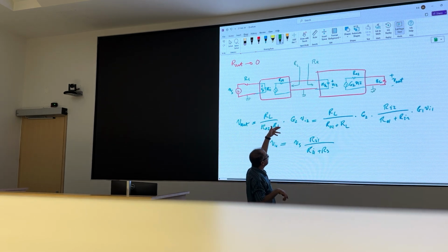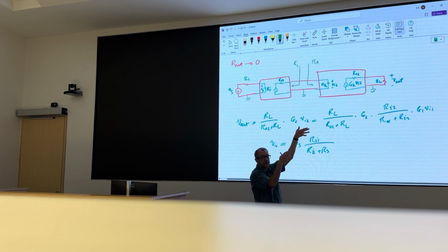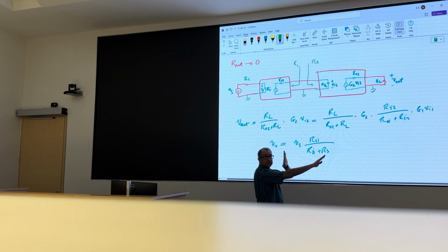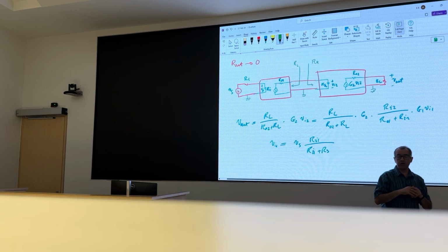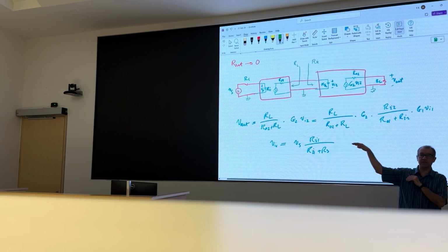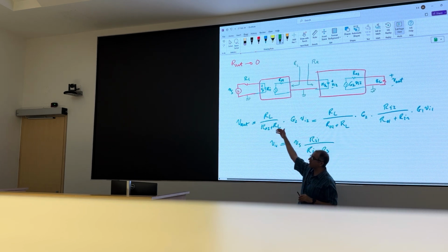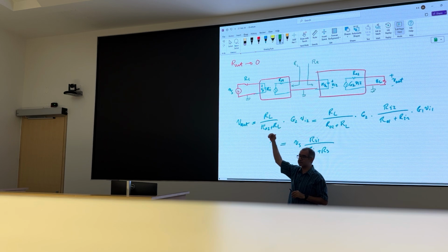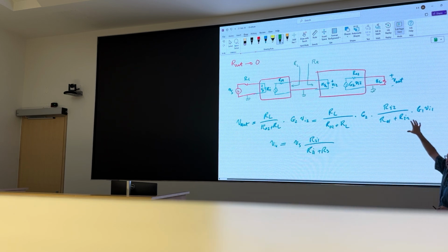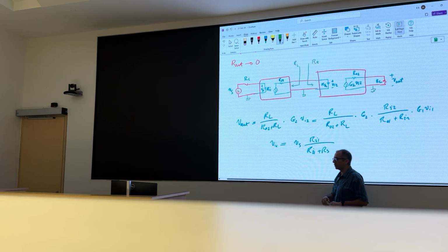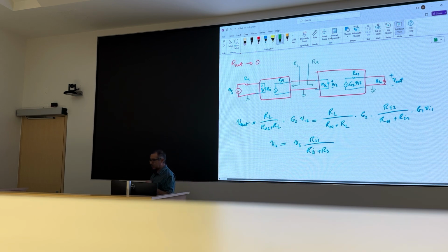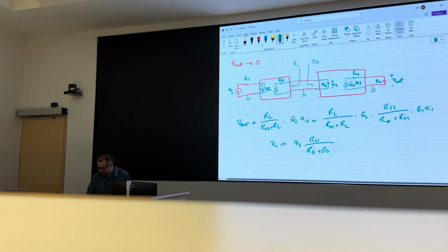What I want to do is measure or estimate the resistance, whatever I have here, if I connect that second circuit to it. Or if I'm a load down here, I want to know the output resistance of that amplifier that is going to connect to it. Or if I'm a source here, same thing. I want to know how much is the resistance that I see. Once I figure those things out, I can create a chain like this and very easily solve my problem. So just go through a couple of multiplications and solve my problem. So figuring out that impedance or resistance is very important.